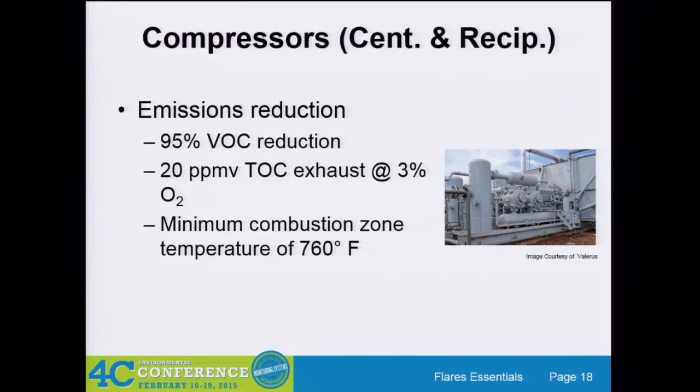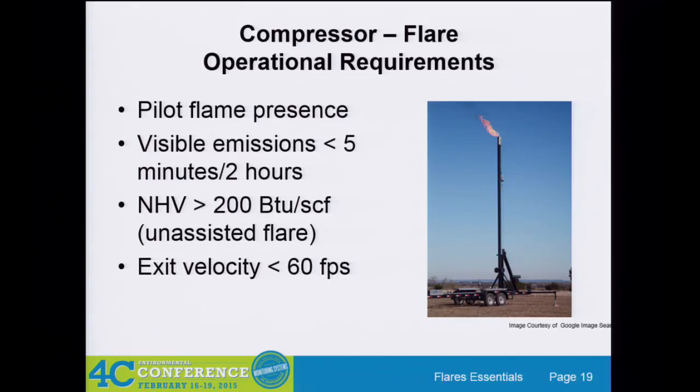What is required? You've got to have a 95% VOC, volatile organic compound, emission reduction, or 20 ppm TOC in the exhaust. And if you use a combustion device, you've got to maintain a minimum temperature. 95% VOC reduction, we've been talking about flare DRE today. That's typically 98 or 99 if you're not over-steaming your flares. Generally in Quad O, the requirements were a little less stringent, and pretty much across the board we're going to see 95% in most of the control requirements.